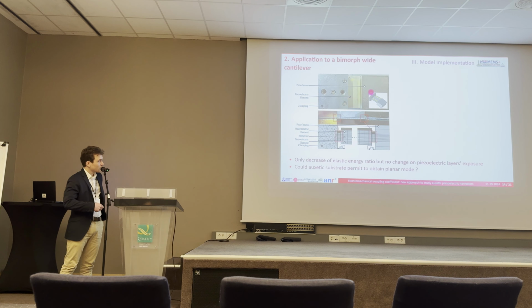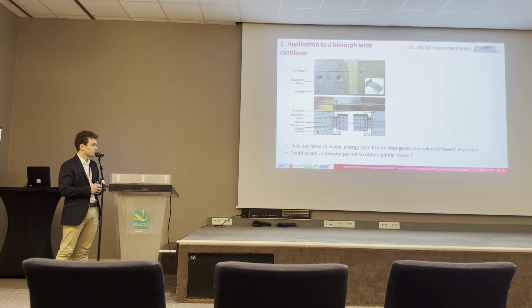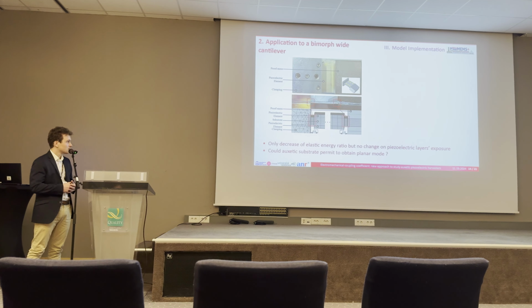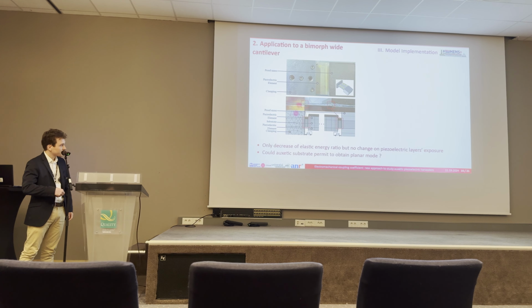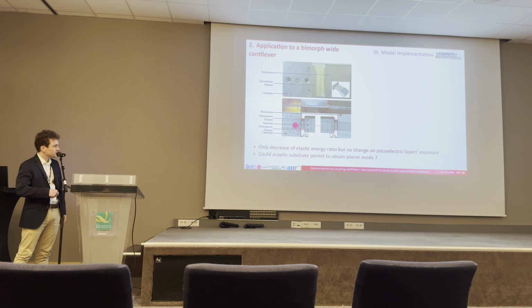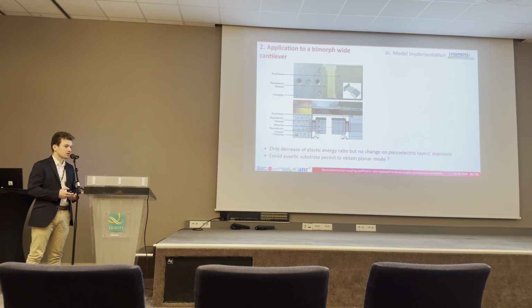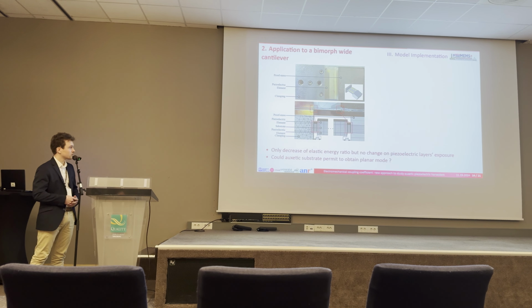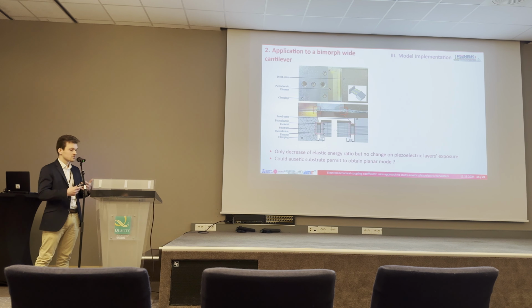So as I said, it's a wide cantilever, so we may think it will have a good material coupling coefficient, as I said before. And we observed that by adding a gap here between the clamping part and the piezoelectric layer, we observe a decrease in the global coupling coefficient, and we might want to know how this decrease happened.